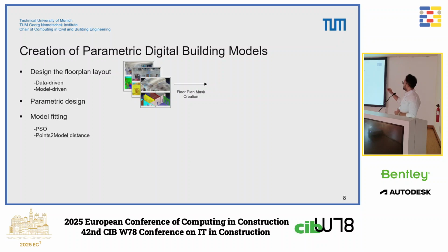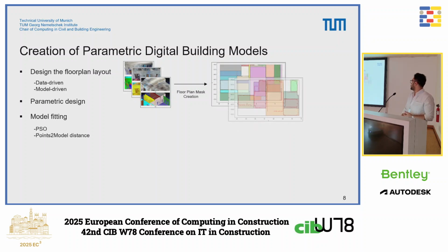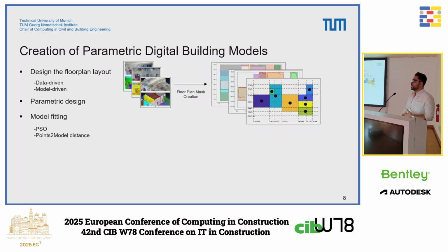In the next step, all the semantic information that comes from the semantic enrichment step is used through a data-driven or model-driven approach to create the first floor plan mask of the environment that actually represents the current position of the walls and layout spaces.